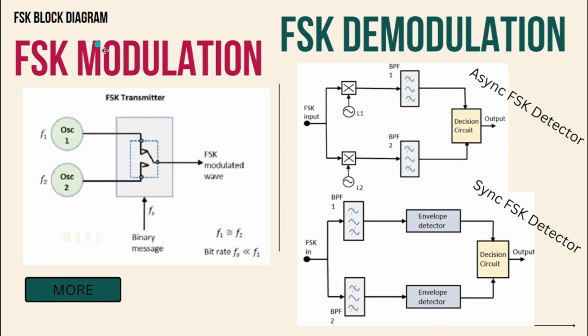The FSK modulator block diagram comprises two oscillators with a clock and the input binary sequence. Following is the block diagram. In FSK modulation, the two oscillators produce higher and lower frequency signals, which are connected to a switch along with an internal clock. To avoid phase discontinuities of the output waveform during the transmission of the message, a clock is applied to both the oscillators internally. The binary input sequence is applied to the transmitter so as to choose the frequency according to the binary input.